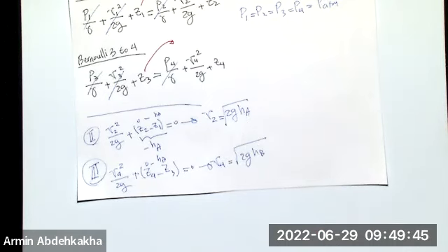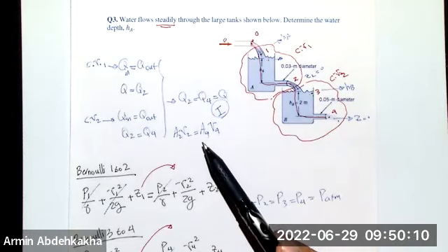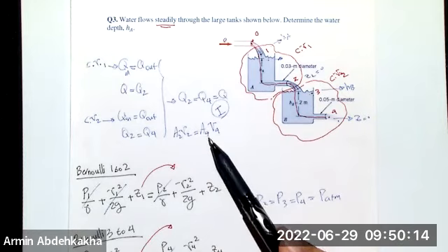If you decided to start with Bernoulli, then here you will start that. I cannot solve it. Why? Because I have to find the relation between V2 and V4 to give me another independent equation, and then solve the system of equations, right? Again, here you can write down the Qs and conservation of mass, and find this equation, which is your equation 1, okay?